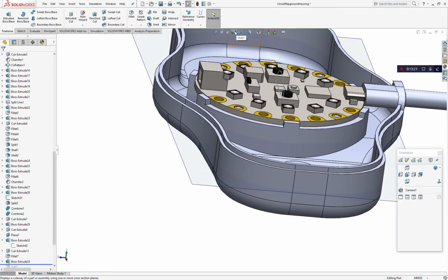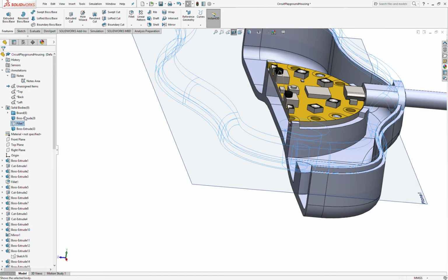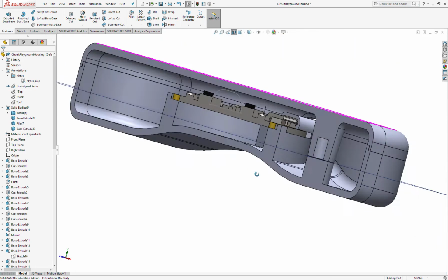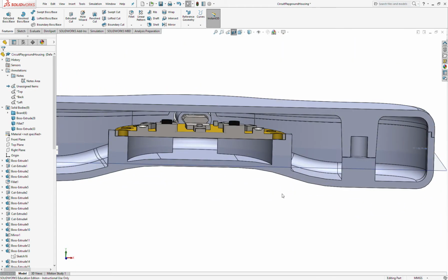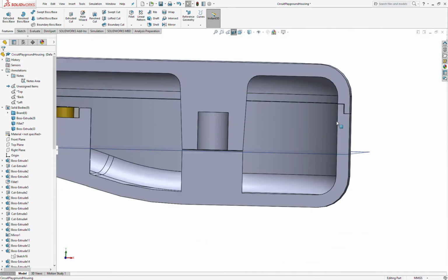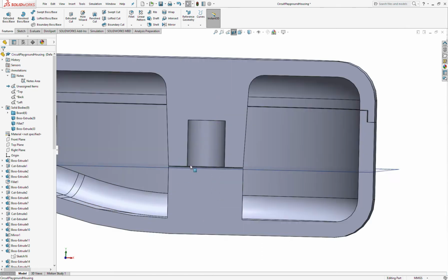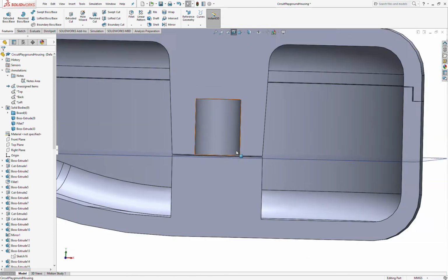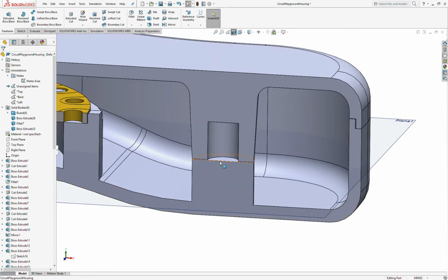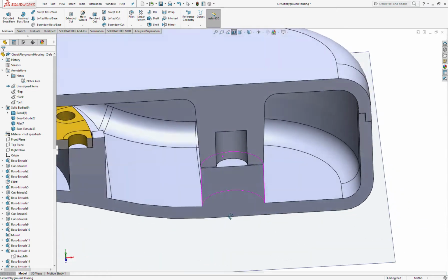So if we do a section cut of this, and we look at these two parts, by not having them touch here, when this housing comes together, these two won't actually be in contact with each other. So it won't bulge weirdly. So now the thing to do is basically to make a hole for the screw that would go in here.